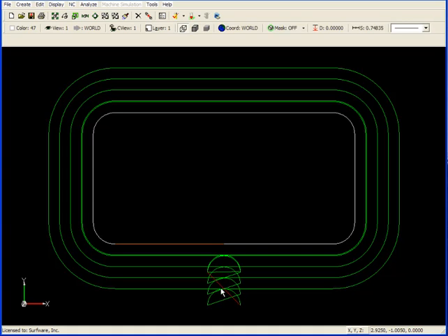An arc move in, around the profile, an arc move out, move into the next profile, and so on. I don't really need that. If I was clearing the material around a boss, I would probably only want an arc move on the final pass, and we can get that very easily.